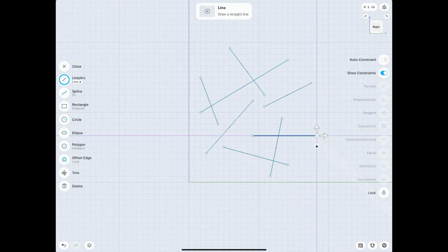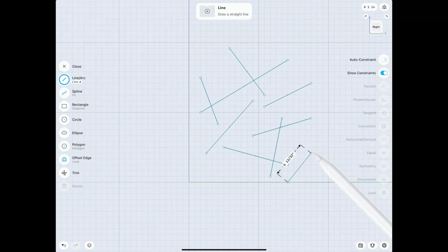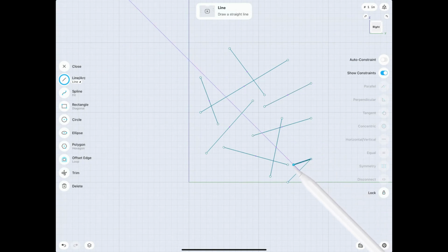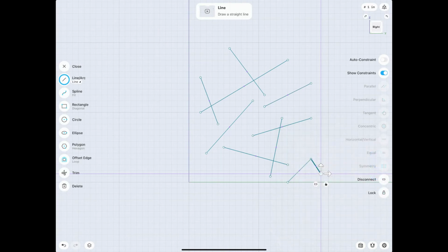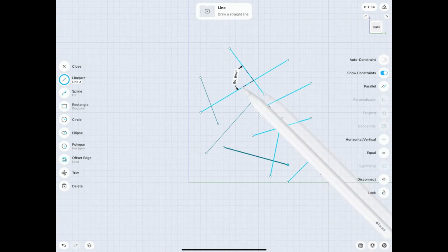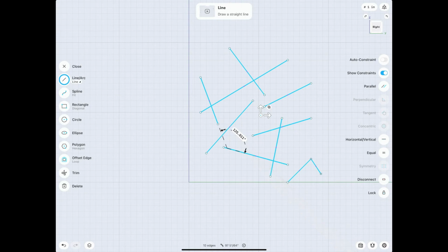If you want to move a point with the pencil, you click on the point, and then via the arrow keys or the center point, we can move this around. You also see there are snapping targets. So it works in many areas very similar to the way SketchUp is. Perpendicular, tangent, perpendicular, horizontally aligned, diagonally aligned. This is where all these guides are coming from. Super good. To delete something with the pencil, we simply tap onto them and then press delete in the toolbar.